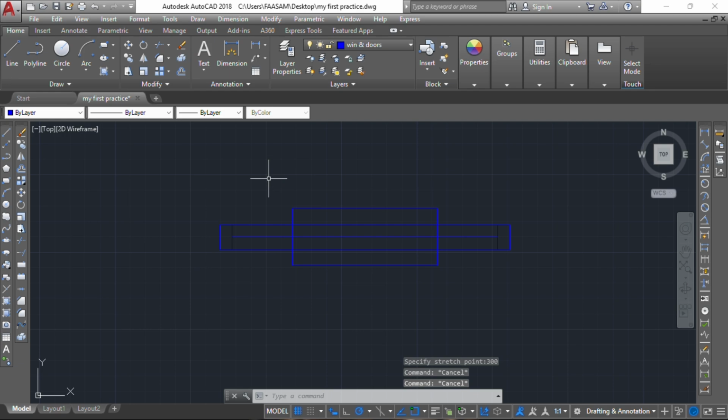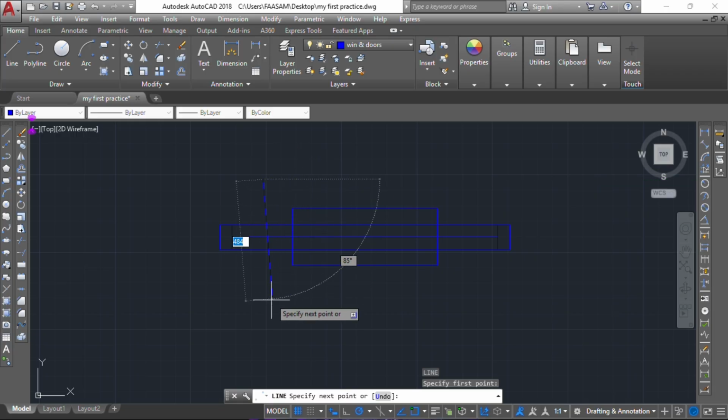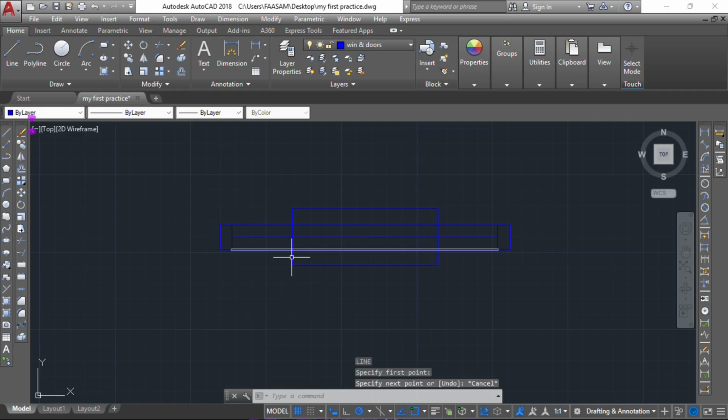And for you to get a straight line, look at something. Let's assume I want to draw a line. I've selected my first point. Now it's showing me this continuous line. Once I give my mouse the direction, it will show me a continuous green dotted line like that, indicating the line is straight. If I'm not having that, then my line is not straight. No matter how I draw my line, be it a vertical line or horizontal line, this is a vertical line now. It's showing this continuously to the down part, right? So it's indicating my line is straight. So anything you are doing and you see that dotted line, then you know your line is straight.